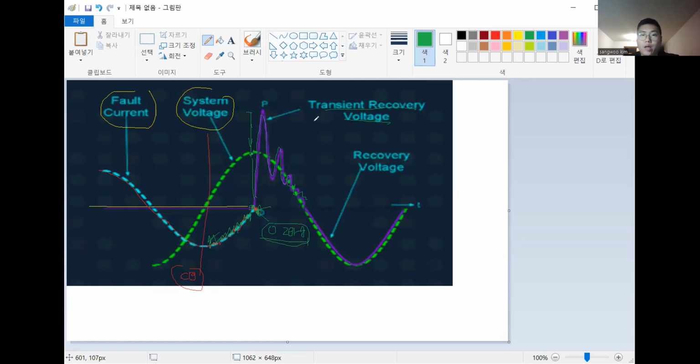First of all, because of the arc's resistance and the circuit's resistance, it cannot be almost two times bigger. The voltage wants to reach this point, but because of LC vibration it would be almost double.